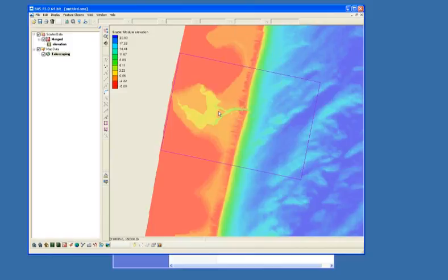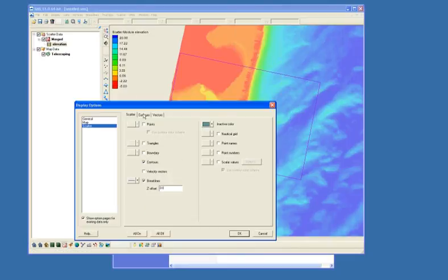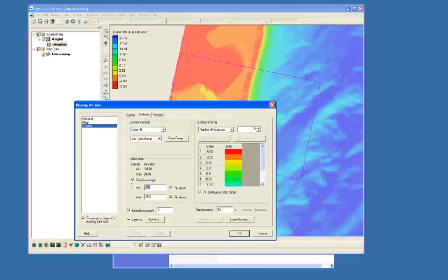What I normally start with is I'll build an arc around where my land is going to be, where I know that my land should be. One easy way for me to figure that out is, you can set your scatter display options, the contours, and on the minimum side, which is the land side, wherever you think that you're going to end your land, you can specify a value.